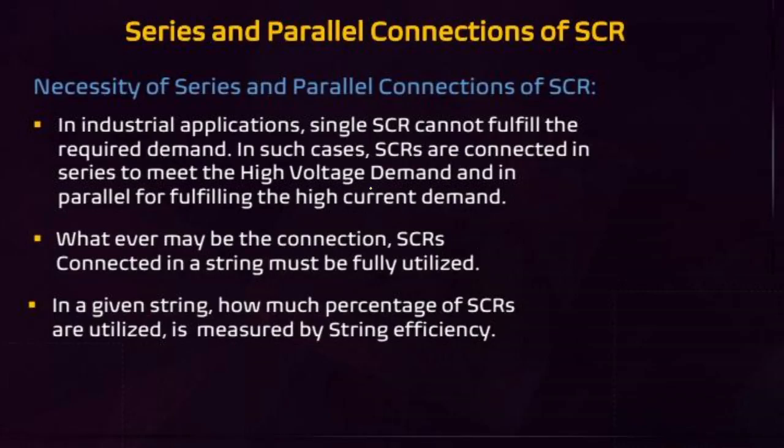SCR series connection is used to meet high voltage demand, because in series connection, voltage is added. SCR parallel connection is used to meet the high current demand. High current demands are met by the parallel connection. High voltage demands are met by the series connection.